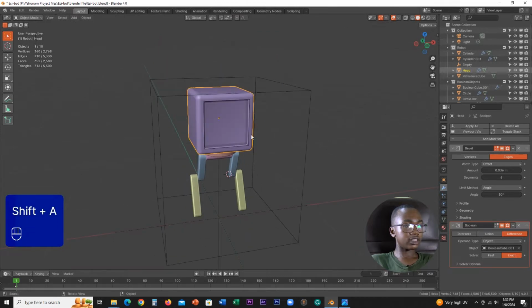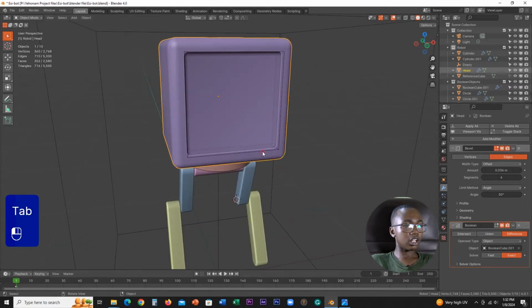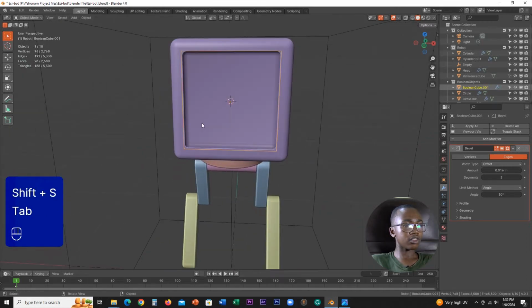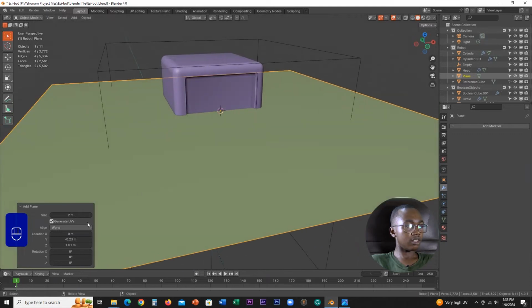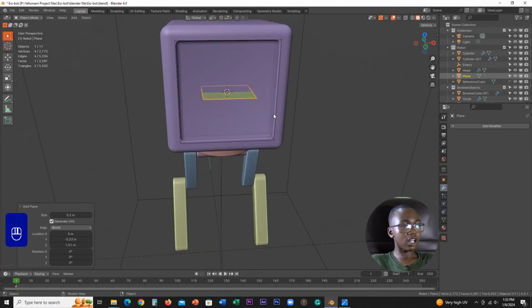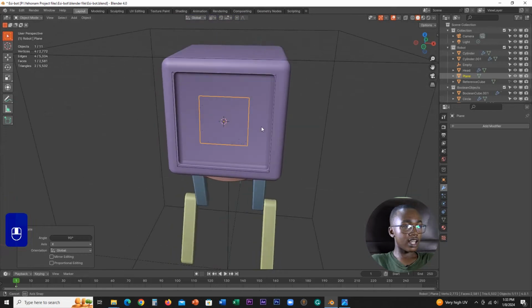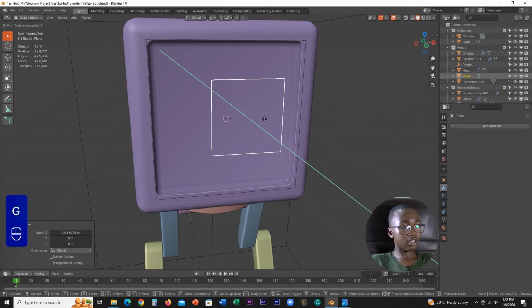What we can do is get a mesh. I want the cursor to be there, of course. Get a mesh plane. Good. Very huge, so you have to reduce it to a size. I think 0.2 is about okay to start off from. So I want to rotate this 90 degrees on the x-axis, and let's model an eye, shall we?